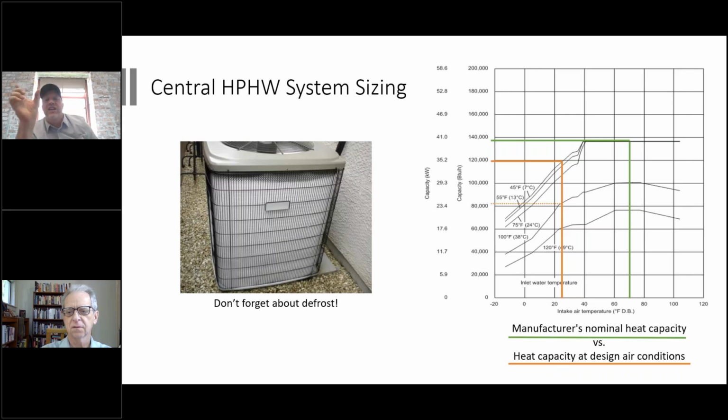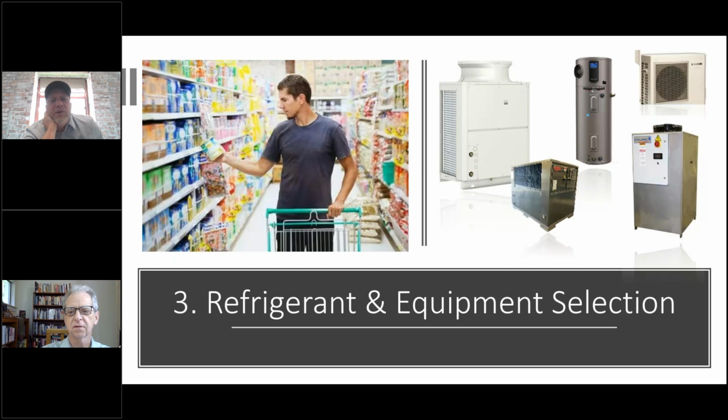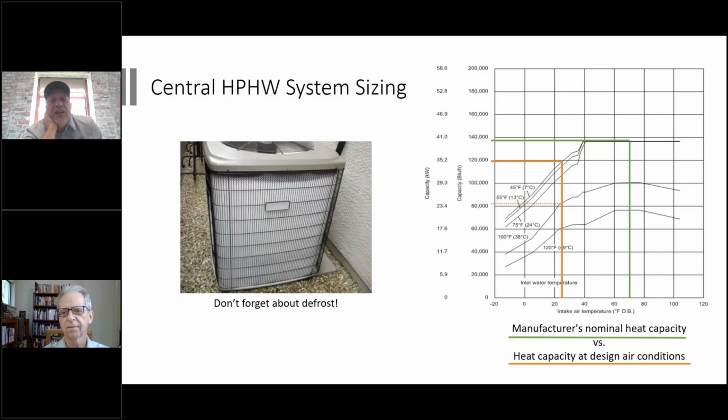But we do most of it in that bulk 35 to 40 because it's really saturated outside and the coils are below freezing. Good. But what you do have to remember is, and the reason to have multiple stages on that heat pump plant is, that you want some to go into defrost and other ones to run, and then if you get enough stages of it, then that impact is minimized.